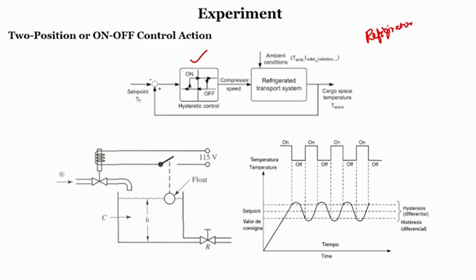So, if you observe, when the temperature increases based upon the set point, the refrigerator will switch on. In order to maintain the set point, it will switch on the refrigerator. Once the temperature is below another threshold value, it will switch off. When you are very close to the refrigerator, you can even hear a tuck sound. It is nothing but the relay switching your power supply on and off, right, even in an iron box.